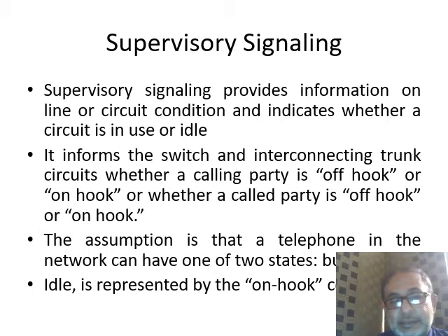Supervisory signaling, basically, as we have discussed, provides information on the line or the circuit condition and indicates whether a circuit is in use or idle. It would inform the calling party's information that you pick up a phone. It would give a certain information to the exchange that your telephone set is off hook now, or on hook if you put it back.